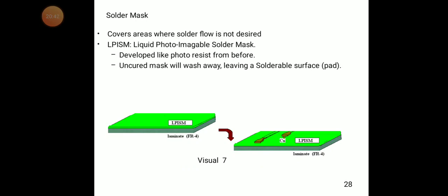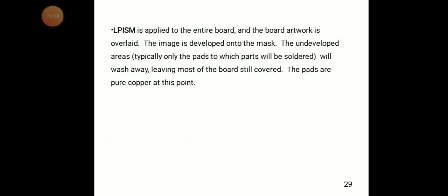LPISM, that is liquid photo imageable solder mask, is used and developed like photoresist from before. Uncured mask will wash away, leaving a solderable surface, leaving a solderable pad.